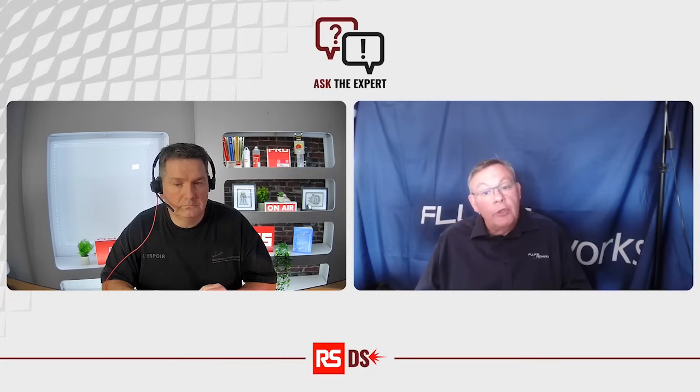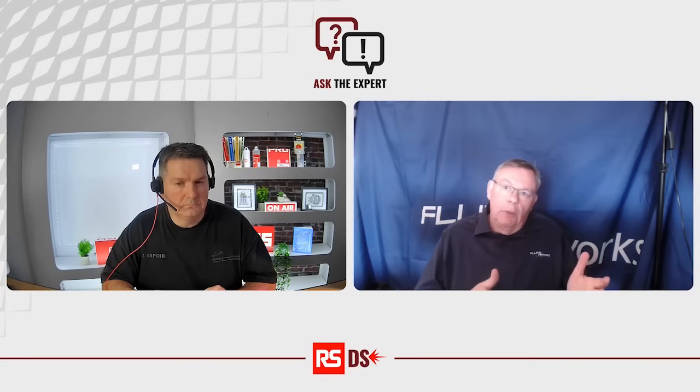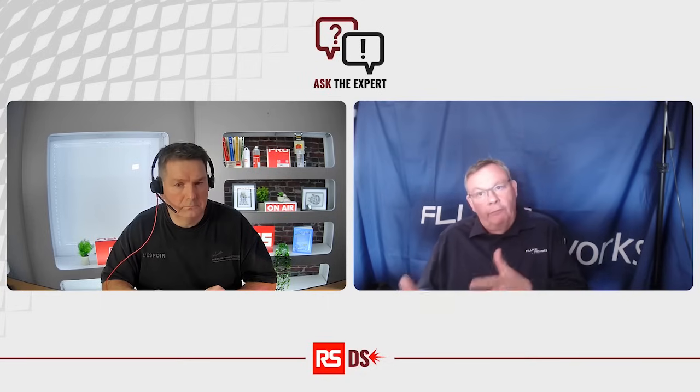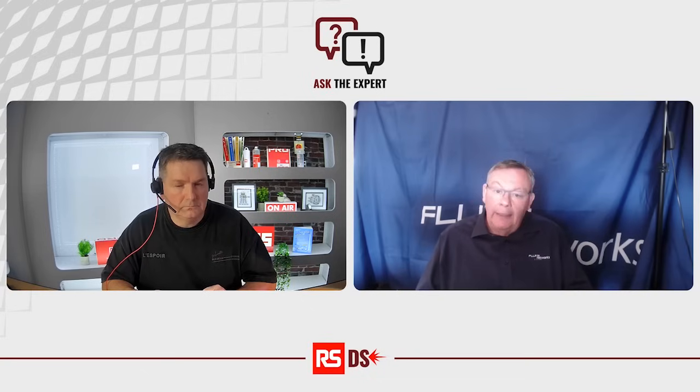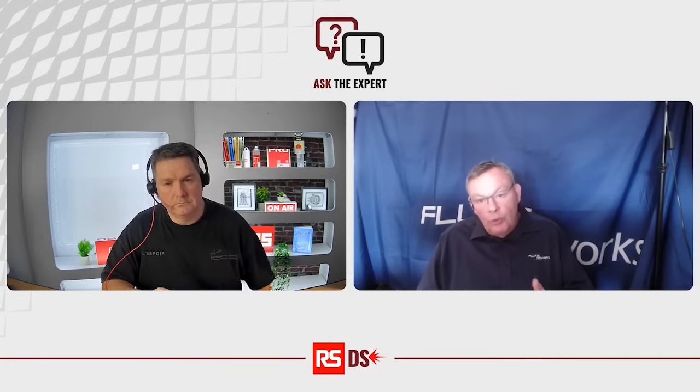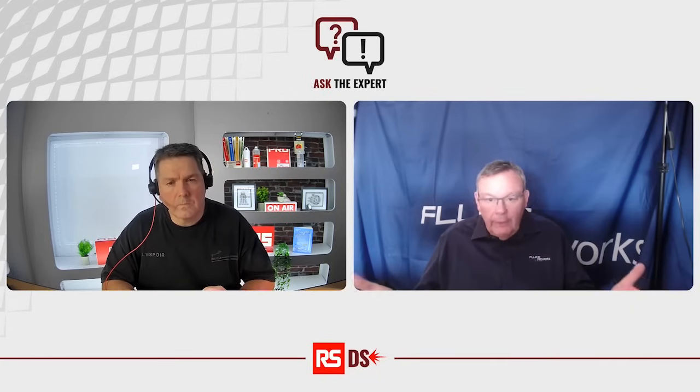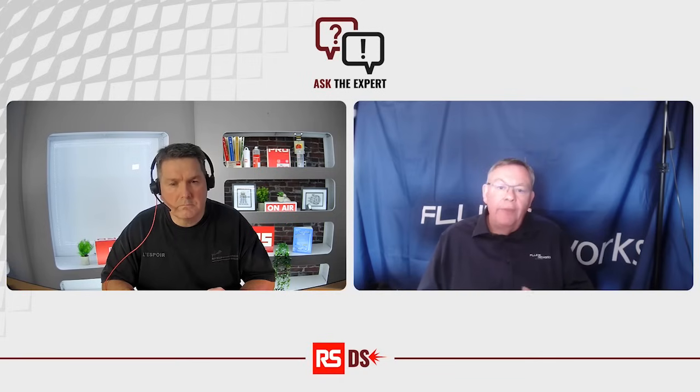First question. So LinkIQ Duo can run a test which uses frequency-based measurement to determine whether or not there is sufficient bandwidth to support 1 gigabit, 2.5, 5, or 10 gigabits per second Ethernet transmission. At the same time, we can also confirm that the length of the cable is within specification, that the noise characteristics of the cable are within allowances,